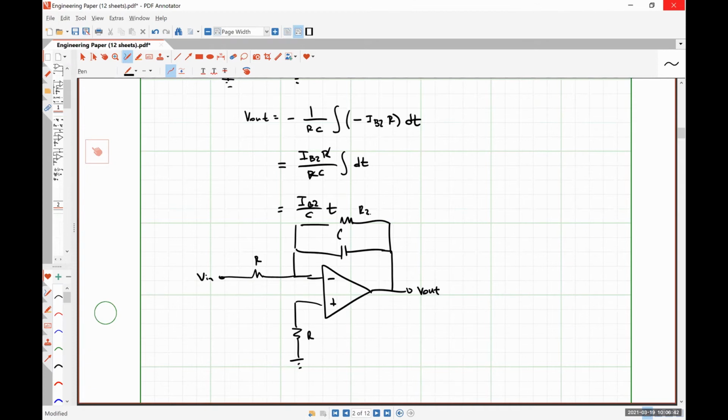So it looks very, very similar to the correction we did for the DC offset voltage problem with an integrator, except that we've added a resistor between the non-inverting input terminal and ground. So I feel like I have beat input bias currents and how to fix them to death. So long story short, put a resistor between the non-inverting input terminal and ground where the size of the resistor is just big enough to cancel out all the currents.